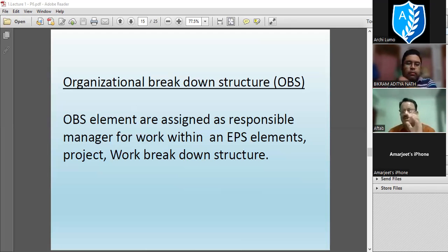So it is nothing but dividing the work into small workable parts, and we go for completing those small workable parts. First we complete foundation, then we complete superstructure, structural part, whether it is RCC or steel, then we complete the finishing part of superstructure, which includes MEP, plaster, paint, whatever. So I tried to explain this WBS in a very simple manner. It is nothing but a smaller division of the entire project. And those divisions, right from beginning up to end, we are completing.